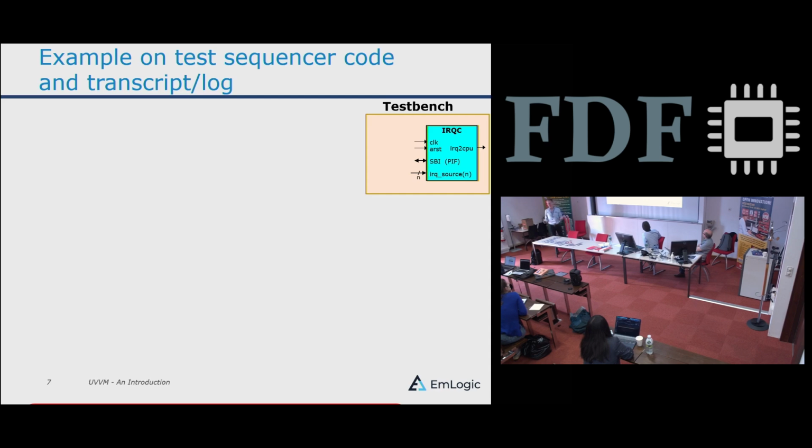And the first thing you need in that test bench is to generate a clock. So you need a clock generator. And then from the utility library, you can directly instantiate a procedure, a clock generator procedure. And remember that when you instantiate a procedure in VHDL directly in the architecture, that's exactly the same as a process. So that's a really, really good way of reusing processes. So just pull that directly out of the library and instantiate that. And of course, lots of different variants of that.